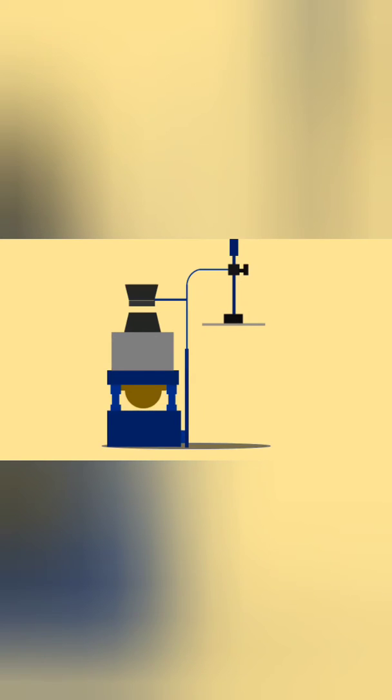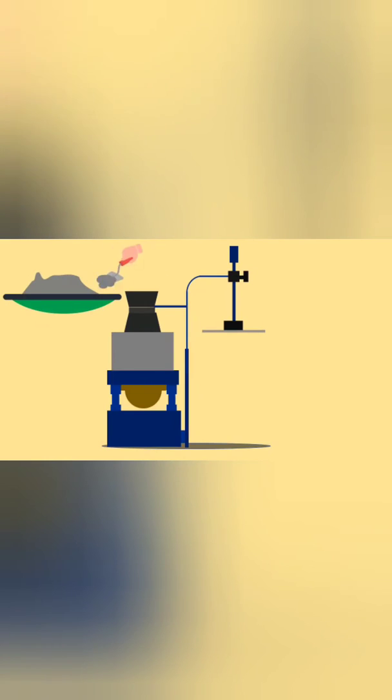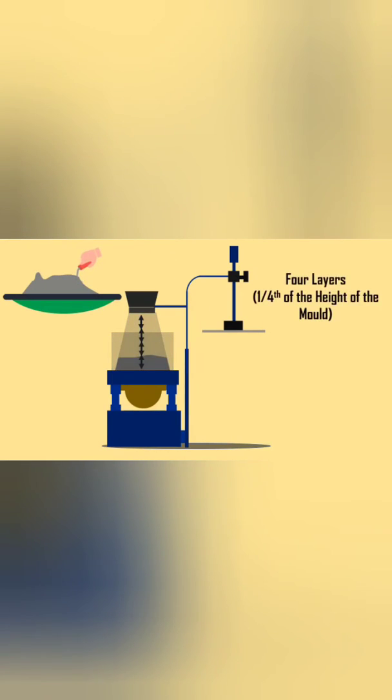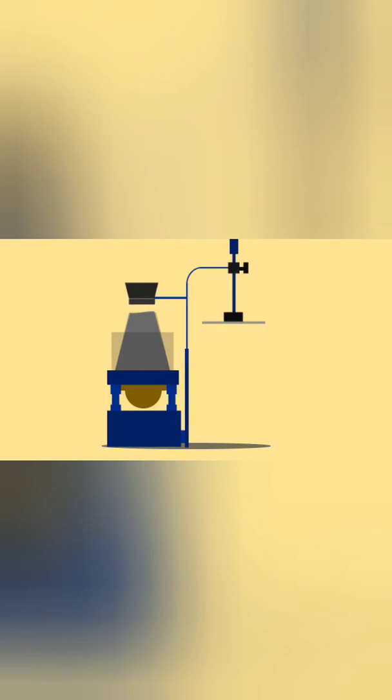Place the slump cone inside the cylinder. Now, fill the concrete in 4 layers. Each layer is 1/4 of the cone height, and tamp the surface 25 times. Once filled, strike off the excess concrete. Move the glass disc attached to the swivel arm and place it on the slump cone such that it touches the top of the concrete level. Note down the reading on the graduated rod.